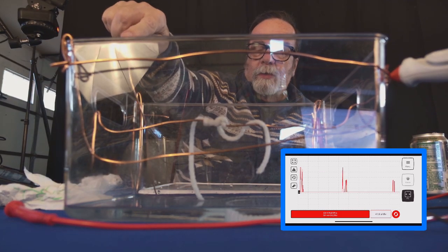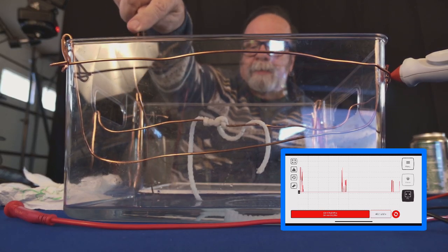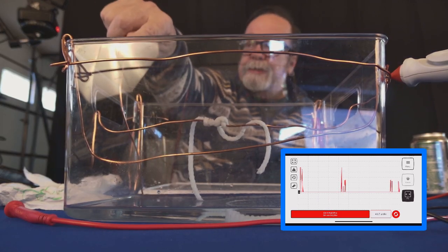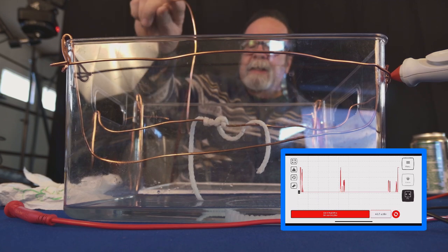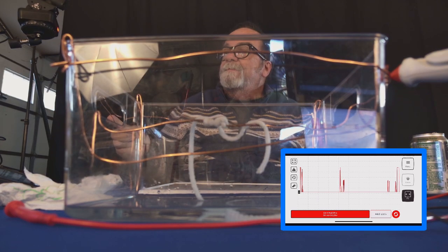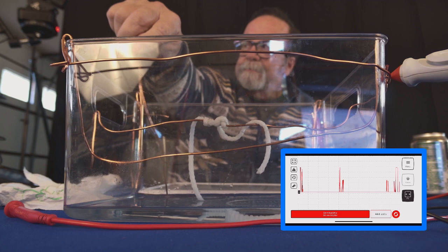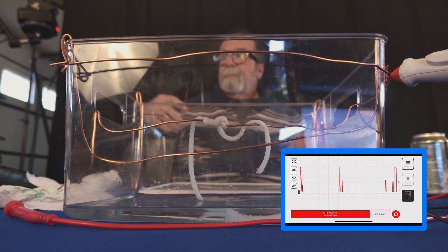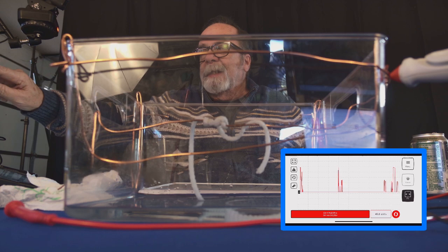So I'm taking this piece of wire inside of here, and I'm intermittently shorting it out. A little bit here, a little bit there, and then I'm going to put a dead short on it. I'm going to leave that dead short there for just a little bit. You can see it goes up to maximum potential, about 95 mils. As I release it, it goes back down. Then if I go back in again and do the intermittent thing, it's going to read it. Now, this is going to allow you to determine that this is your problem, okay?